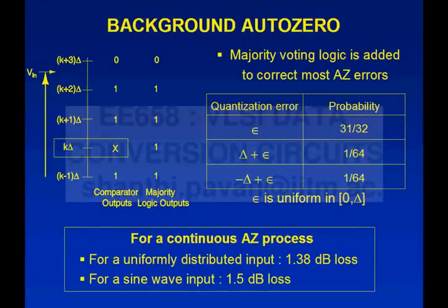When this guy is out of action, you have one extra comparator. You know that you're going to pull this guy out. So you charge up the references to that comparator before you pull this guy out, and then replace that electrically. Physically you can't replace anything because this is all laid out, right? It's all hardware. So electrically you must somehow disregard the decision made by the comparator which is being AUTOZEROed, and instead use the decision made by the spare guy, and then everything remains.